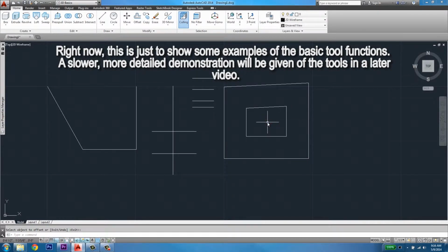segment in that direction. The Trim command trims objects at a defined cutting edge, such as an existing line. The Extend command does exactly the opposite by extending the selected line to meet another object. A Fillet rounds off the intersection of two lines.